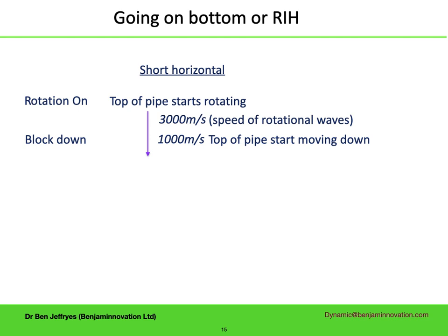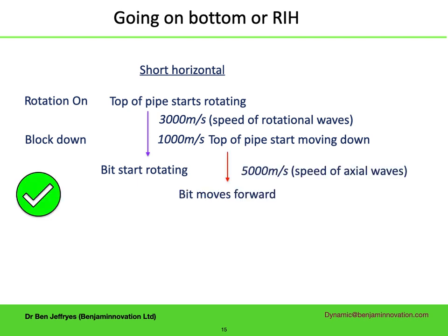It doesn't matter if the bit hasn't started rotating yet, so long as it is rotating before the axial wave arrives at the bit. And it's all good. The bit is rotating and moving forward, smoothly going on bottom, or along the wellbore if running into hole.